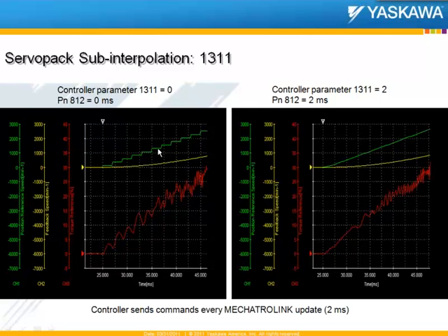Every time a step change happens in its command, the servo pack essentially has to send out a large change in the commanded torque. As you can see here, every step it commands a large change in the position that it needs to jump through. So it's almost like it's going through multiple steps, and that can be harsh on the torque requirements for the servo pack.